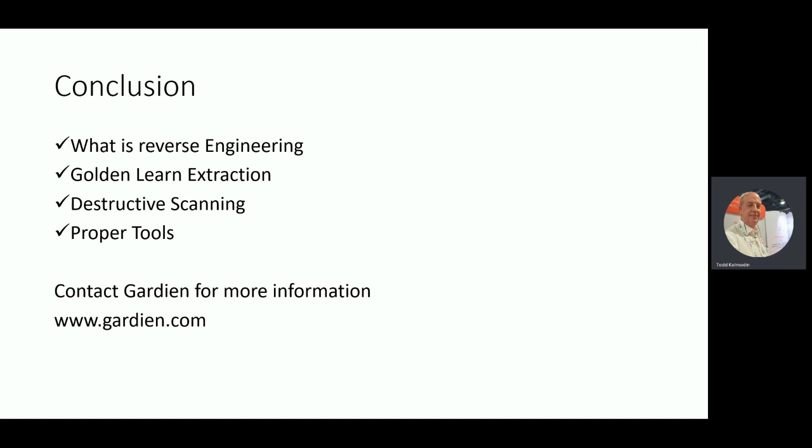And then the last thing I talked about was having the proper tools, basically having a strong enough scanning platform to get high pixel resolution, and you want to have the right equipment to be able to do the self-learn or the integrity test of the PCB prior to scanning, and then actually post-scanning if you have the ability to do that to the board, or you can do the netlist comparison between the original self-learn prior to destructive analysis, and then you can compare to make sure that you're absolutely correct or make any adjustments. And then those photo tools are ready for the manufacturer to recreate the PCB.